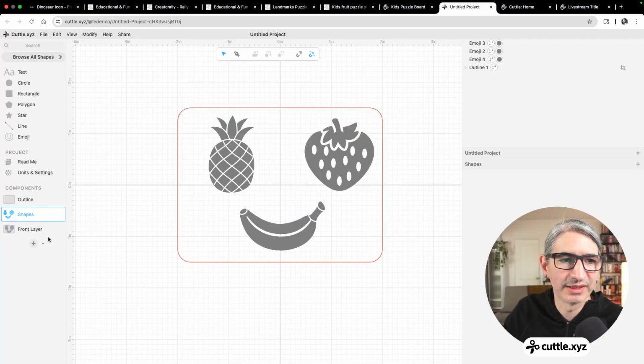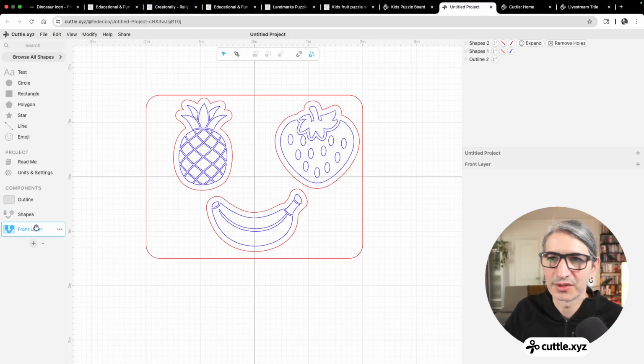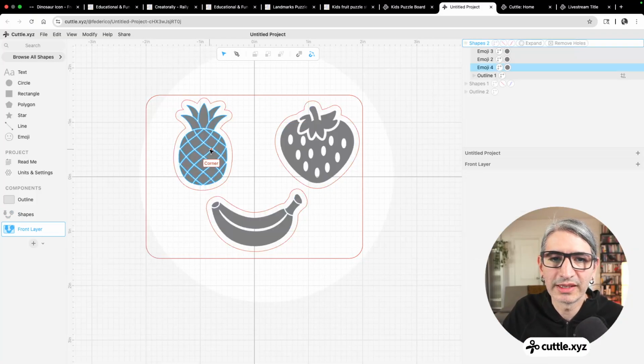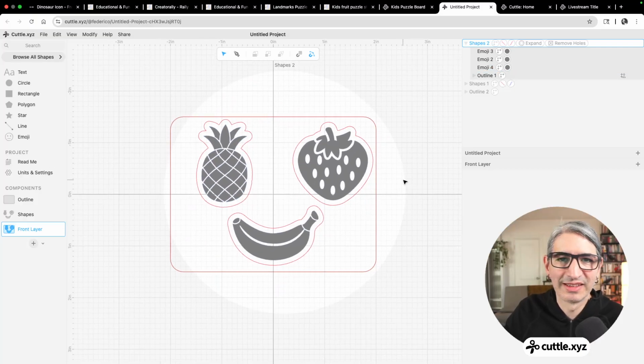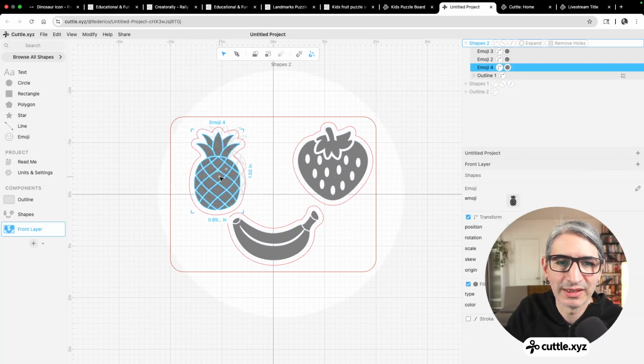This is also another way in which I can show you what is editing in context, which is I can double click into it. And if you look, it creates this kind of spotlight, and it gives me the name of the thing I'm editing up here. So I'm editing an instance of shapes. If I edit in context right here, it's actually editing the shapes component, but it's letting me see all the operations I apply to it.